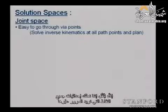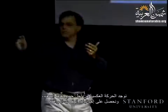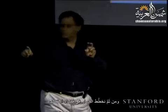So let's say we have the coordinates of each of the points that we want to pass through. We solve the inverse kinematics for all these target points. We get the corresponding joint coordinates, and then we plan in joint space the trajectory. Okay? So that's pretty simple, and it's much less calculations.